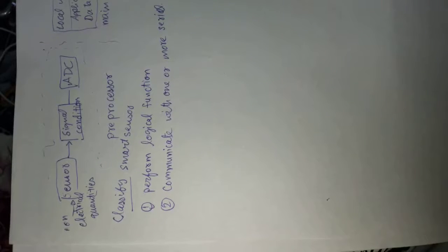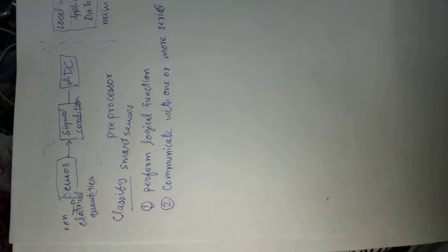Signal preprocessor converts or carries out low level tasks such as amplification, as we have already discussed. Suppose I need any computation, I must have a processing unit or a processor. So this processor can be an 8-bit processor, 8085 kind of thing, and most of the tasks can be done by 8085. It does not need a hi-fi or a very complex processor as a preprocessing unit.